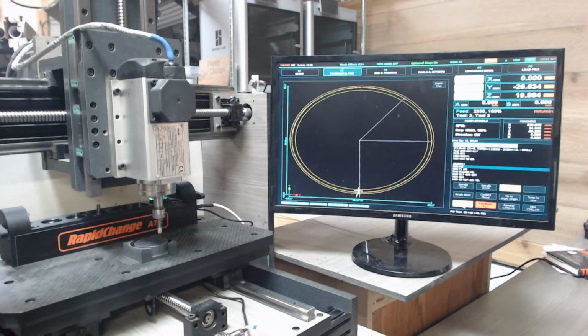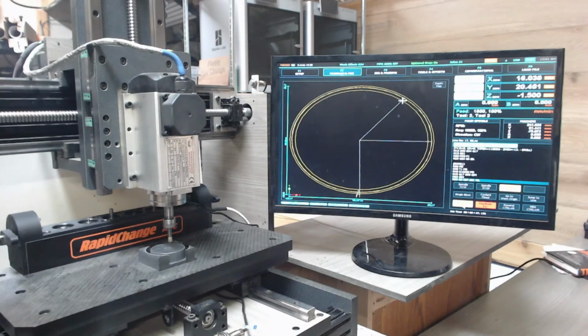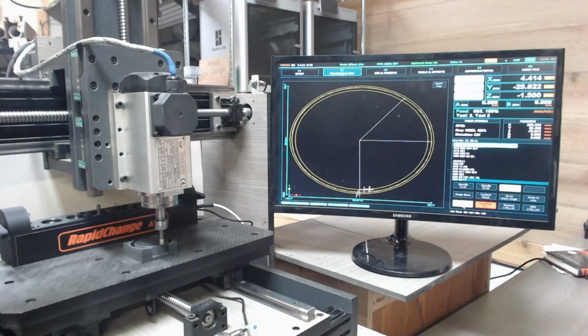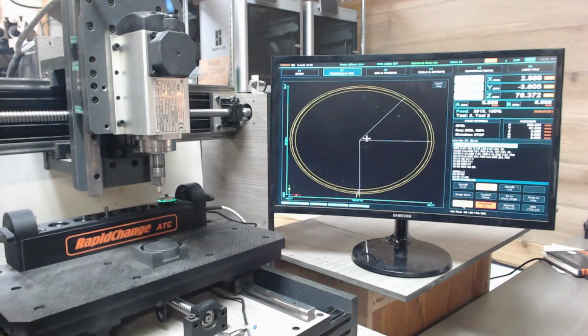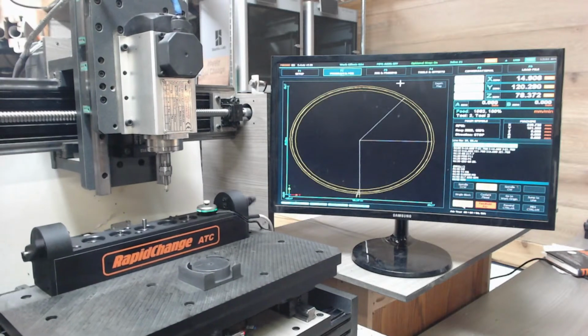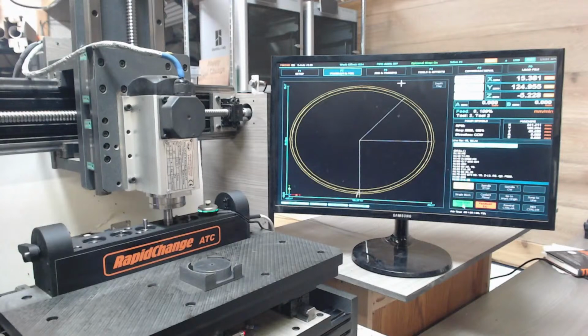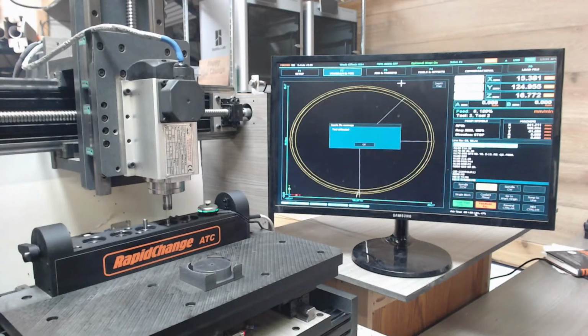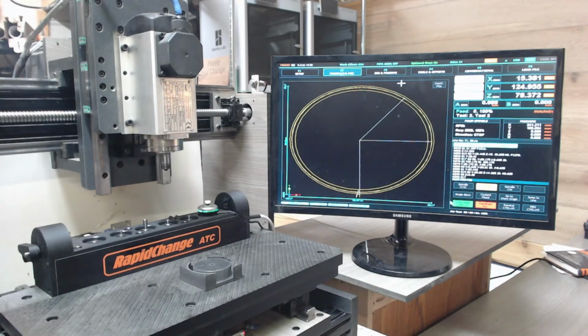This is going to be the last tool path, and then I'll run the loop file. And it's going to unload the tool with the Masso. You got to unload the tool at the end because the tool change is actually happening in the post processor file and not in the M6 functionality. The only thing the M6 functionality of the Masso is doing is setting the tool length offset.